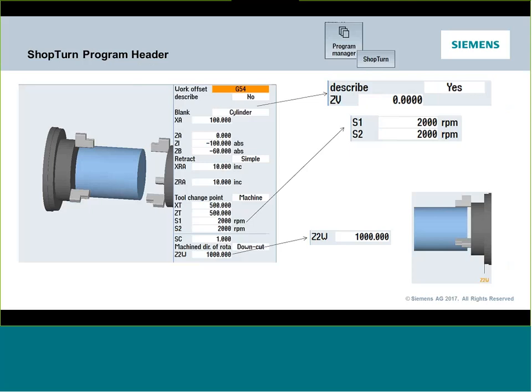I did that all through the process setup. But in a machine like this, I know where all my values are, and I can easily figure out where my dimensions are. So in this case, you might want to use describe, and this way, if somebody goes in and changes an offset inadvertently, it doesn't matter, it's going to get rewritten anyway. So it's pretty common to actually use describe here. Later, you're going to see the describe function for the sub spindle too, and there it becomes extremely handy because it does all kinds of calculations for you.